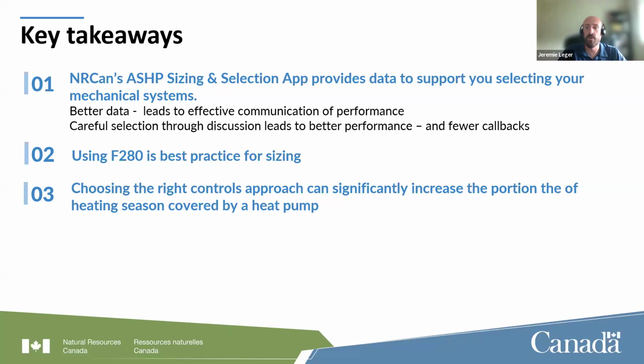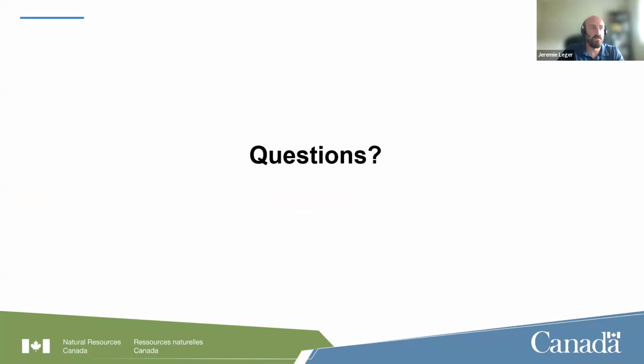And finally, choosing the right control approach can significantly increase the portion of your heating season covered by the heat pump. So just because you've spec'd a really good heat pump, it doesn't necessarily mean that you're going to get the best outcome out of it unless you control it properly. So be very choosy about your control options and make sure that it aligns with the objectives that you're trying to achieve. And with that, I think we have a few minutes to take questions.